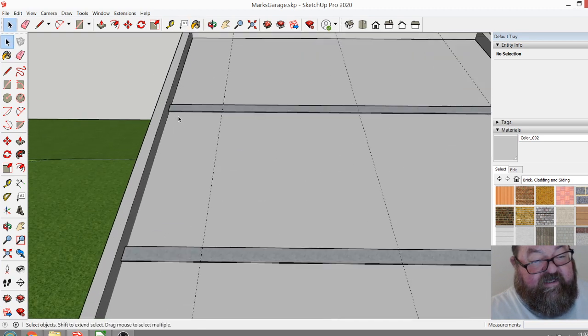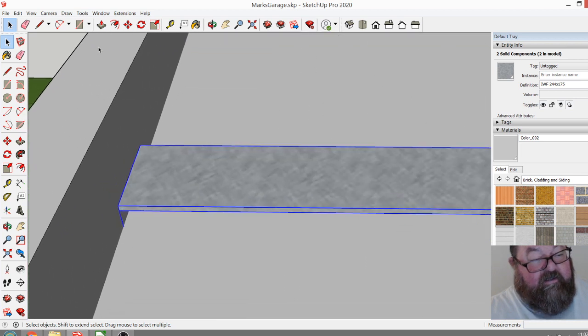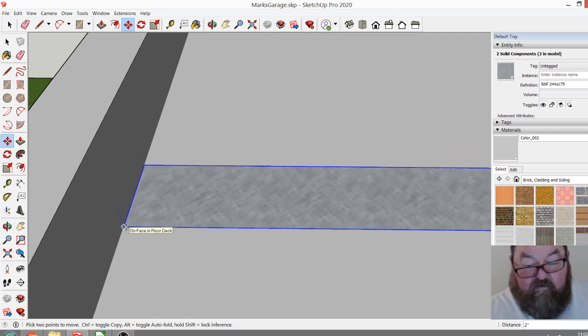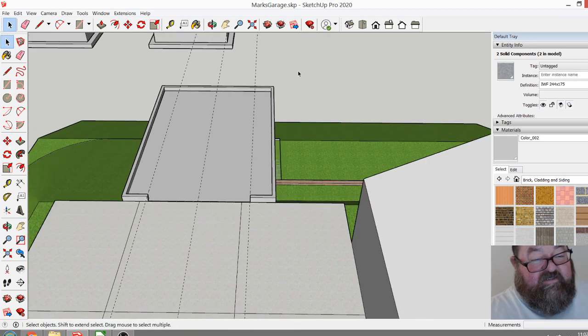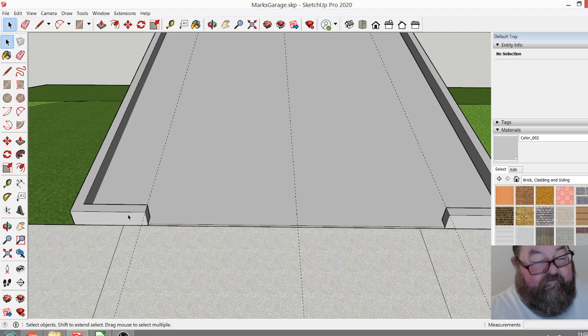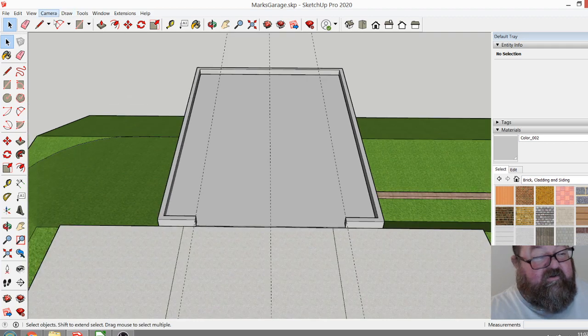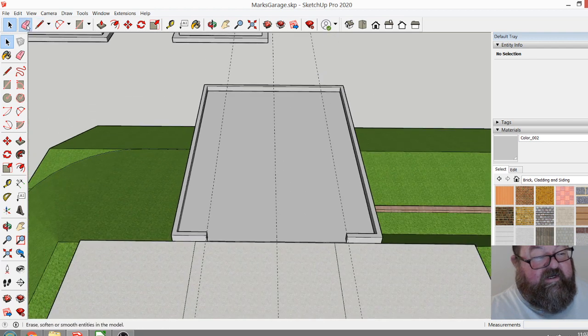And now you can see our steel beams need to go down, what, 6 inches? That would be 8 inches. There we go. And we're back in business. And that's what you want. You want this little stump here of concrete so that your front wall is not sitting down where water's always running against it.